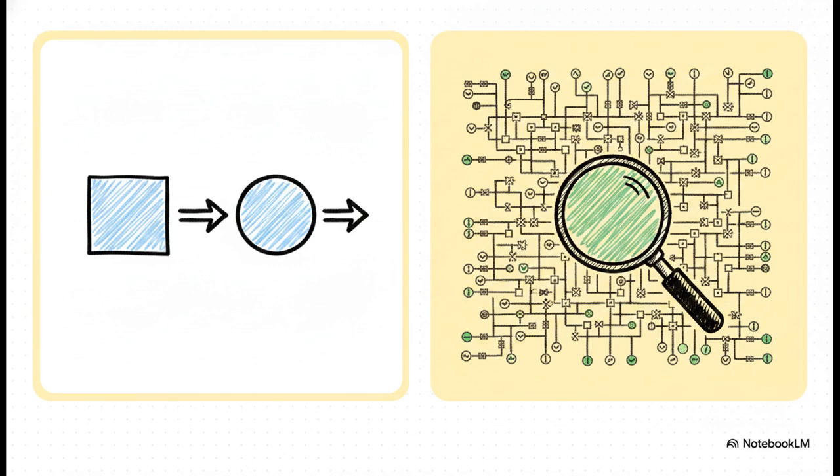First, engineers start with a process flow diagram, or PFD. This gives you the broad conceptual strokes, the fundamental process design, major equipment, and primary operating conditions like flow rates, temperature, and pressure. But when it's time to actually build, operate, or troubleshoot the plant, that's when you need the piping and instrumentation diagram, the P&ID. This is your detailed, meticulous mechanical blueprint. It shows absolutely every single interconnection, all the equipment, exact piping specs, every valve, and all the complex control instruments that keep the system running.